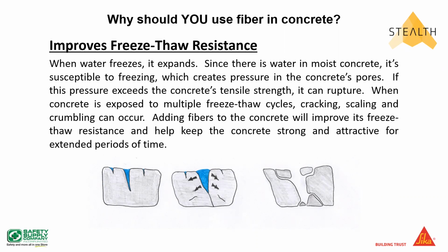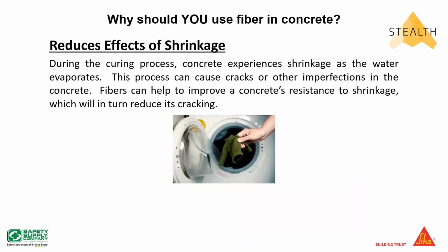Those three little drawings you're looking at show what the water does when it freezes: it expands. When it expands, those forces and pressures go somewhere, and they cause the concrete to crack. So fibers can help hold those cracks tight. Even if it does crack, it will certainly hold them tighter than if nothing was there.